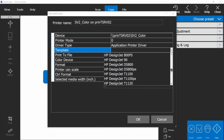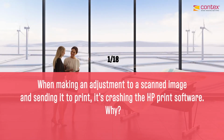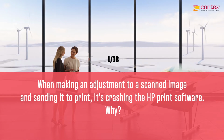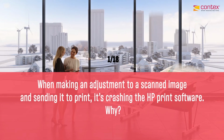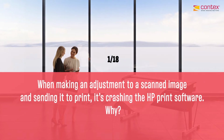But you want to verify, just in case somebody's made a change someplace, that the template is set to the printer that you are attempting to output to. So you want to make sure you're using the application driver and you have the correct template set. Usually it's going to be one of those items that cause the most problems, so that's the best place to start.